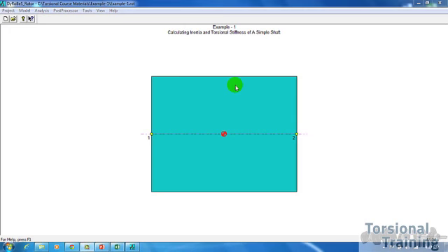Now, before we move ahead, I'd like us to carry out a hand calculation of this exact shaft that we've modeled: calculate the torsional inertia and the torsional stiffness. From our hand calculations, I'd like to then compare those numbers with the numbers that Dyrobes calculates, and that'll give you a really good understanding of how to calculate torsional inertia and torsional stiffness.